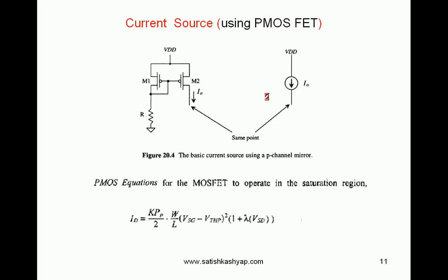So this is regarding the calculation of three important parameters of the simple current mirror. One is current gain, the other is output impedance, and the last one is V naught minimum required to keep the output transistor in saturation such that a stable I naught results. And after that, what we have discussed is how to implement the PMOS current mirror.